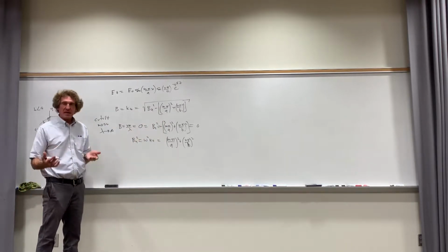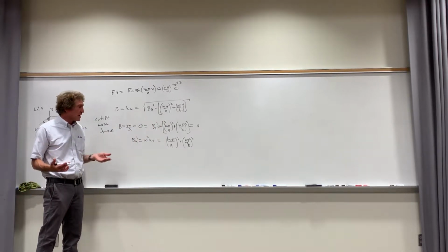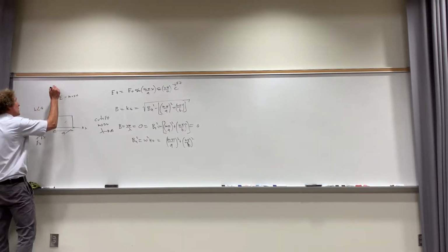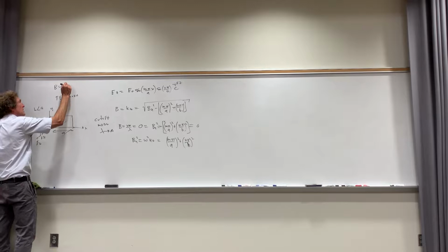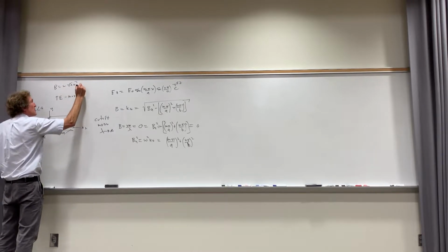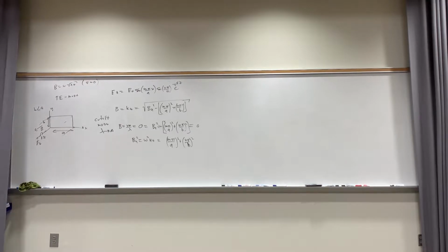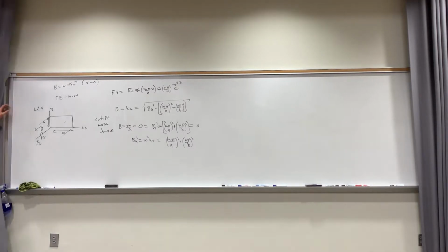And then I defined what beta unguided is. It's really omega squared times mu epsilon. Because beta, remember, beta is just omega times square root of mu epsilon if sigma is 0, if it's lossless. Do you all remember that, class? I don't know if you do or not, because some of the stuff, unless you use it frequently, it doesn't stick with you. But does anybody know where that comes from?